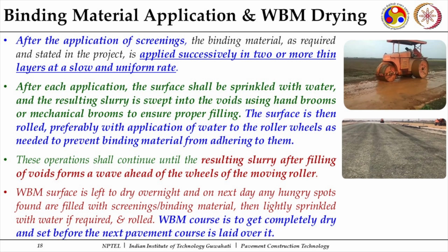It mentions how much binding material is to be used for a particular grading of screenings. The binder is applied successively in two or more thin layers at a slow and uniform rate. At least two to three layers are to be applied, so that finally it goes inside the voids and gives you a good surface.